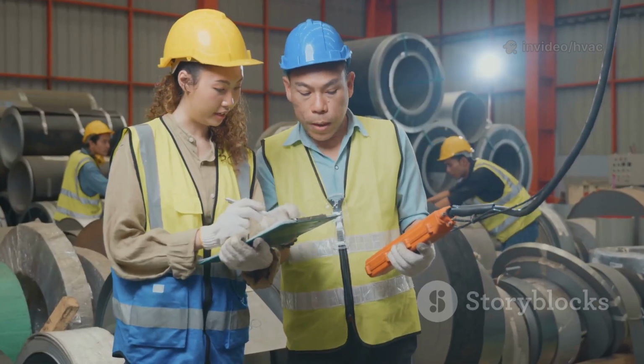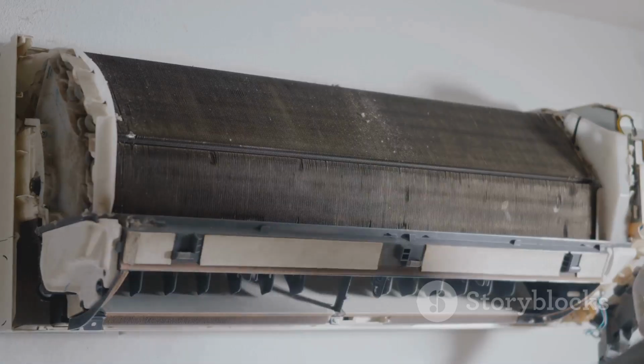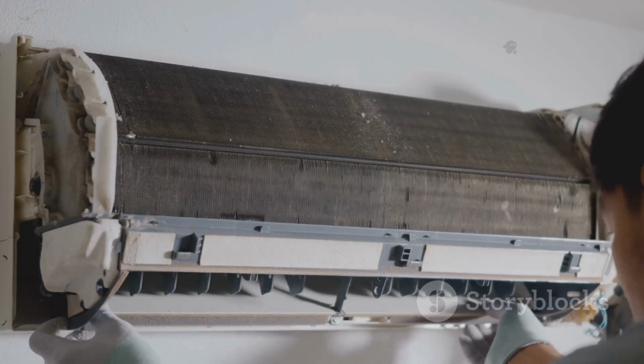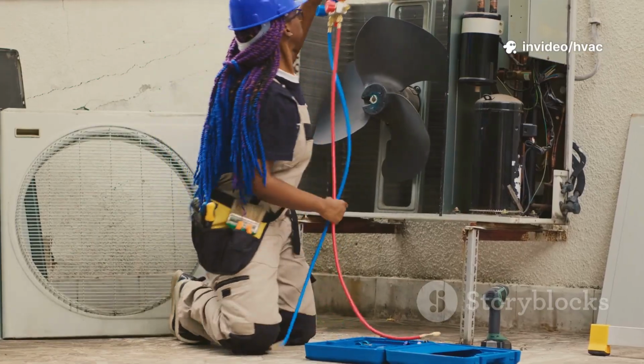Sizing is similar to ducts. Measure the coil's face area, height times width. Find these dimensions on the mechanical schedule or submittal data. For example, a 4-foot by 5-foot coil needs a 20-foot sensor.